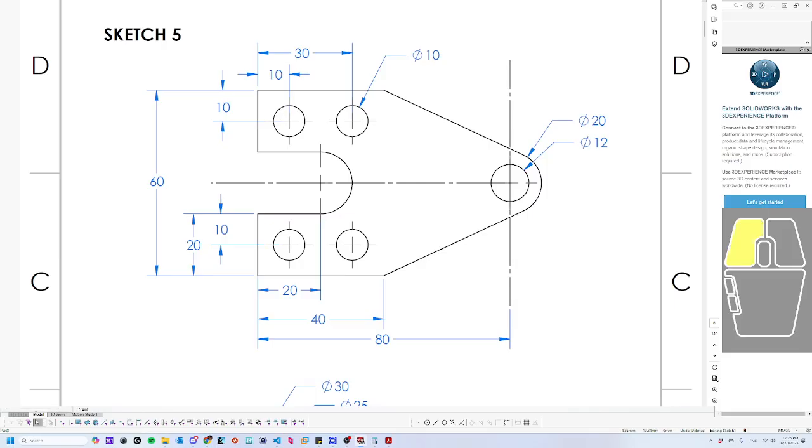And this line here, I at least want it to be symmetrical with this line below it. So I'm going to make those symmetric. All symmetric does is match the angle. It doesn't actually match the entire line itself. Okay. And then going around, I want to make this point here in line with this point. So maybe I'll make these 2 vertical. That's locked in part of this up here, which is nice.